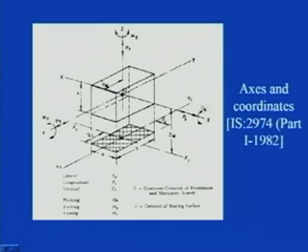This will cause the pitching motion of the block foundation. Then along y, this will cause a rocking motion of the foundation, and if it is rotating along the z axis, that is in the horizontal plane, then the motion is called yawing.